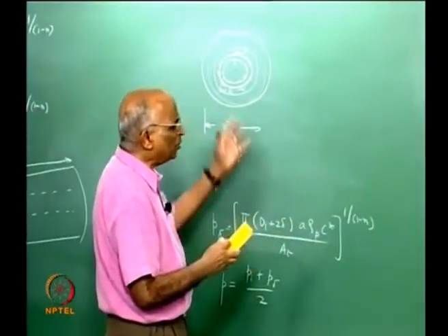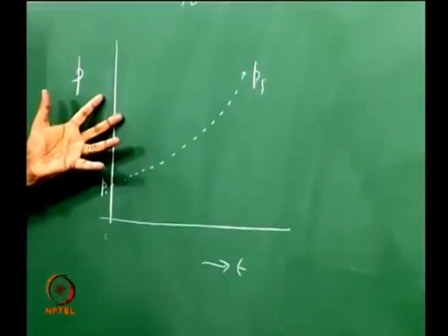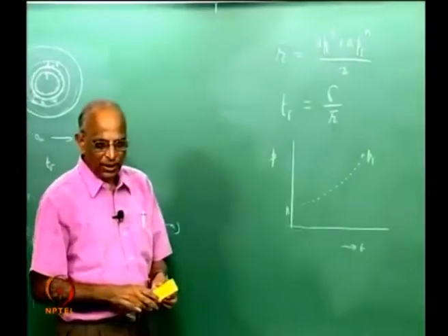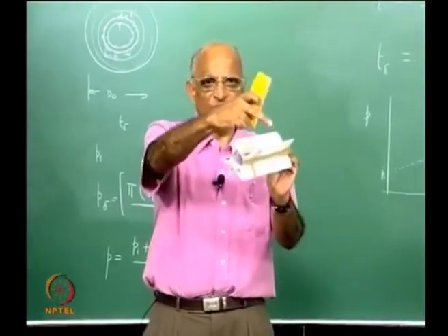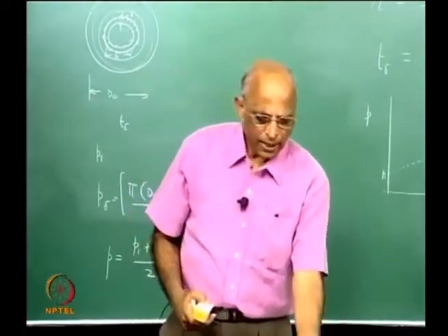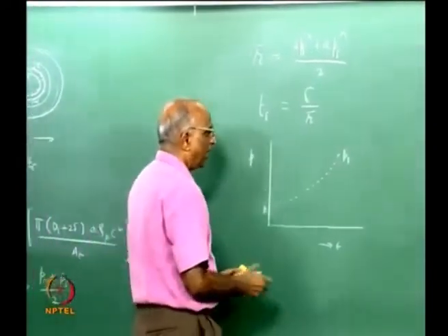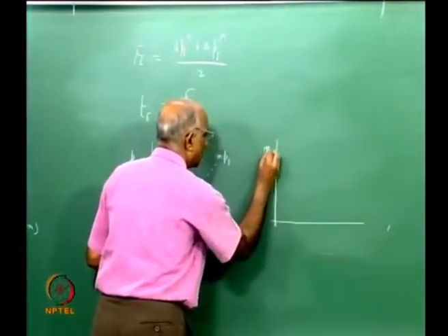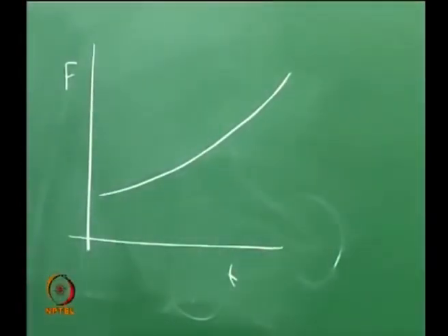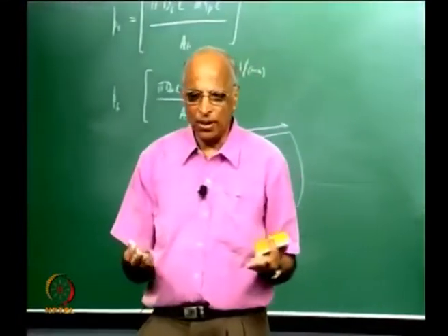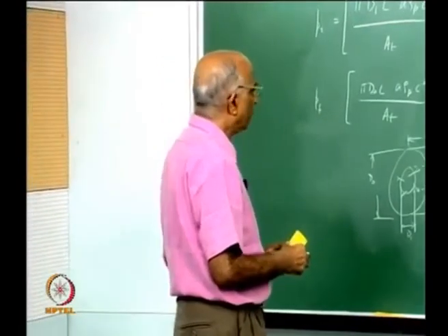We can do this, but this is a numerical way of doing it. There is no other way, and this is the way to do a problem, because when I have a more complex configuration, like I said, I wrinkle the inner surface and get all these shapes, I can find out how the surface should evolve with time. This is how one calculates the variation in pressure with time. Once I know the variation in pressure with time, I can readily say that the thrust characteristic with respect to time will also change in this particular way. This is how a solid propellant rocket involving radial grain is made.